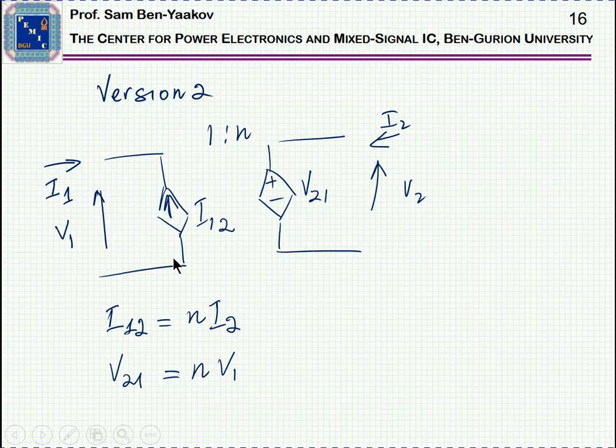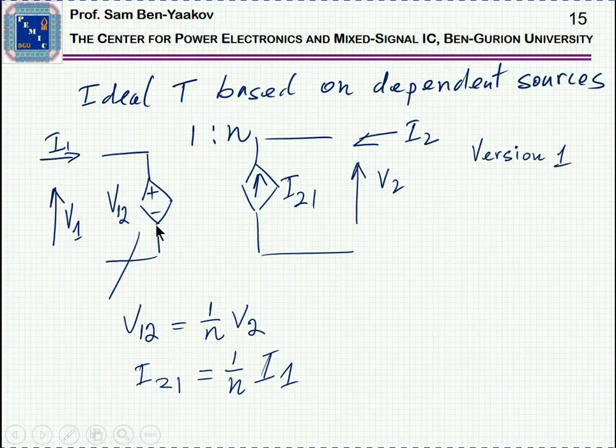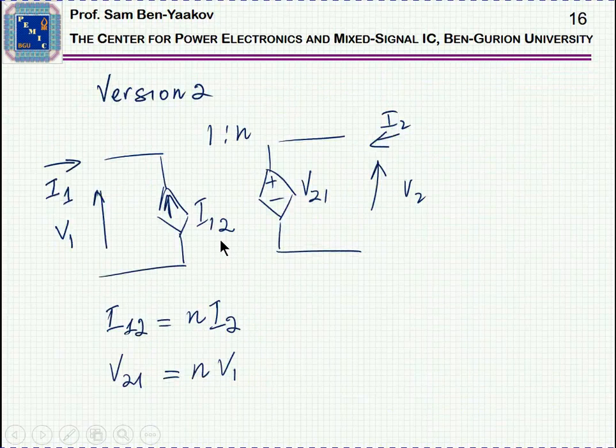So in this case, you'd like to go to this representation in which there is a voltage source, which will be easier for the simulator to converge to the solution. So you can use either one, and as I've said, you can build it yourself, or some vendors are actually implementing it and calling it an ideal transformer, and what it is basically is dependent sources.